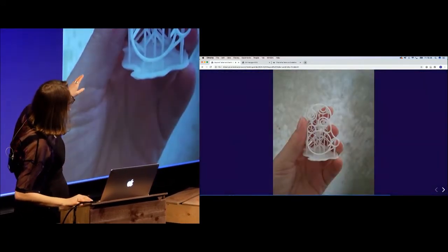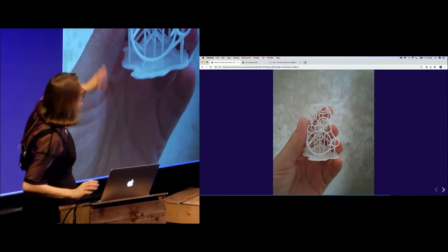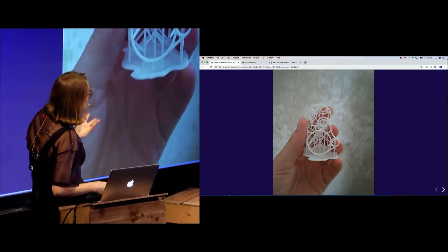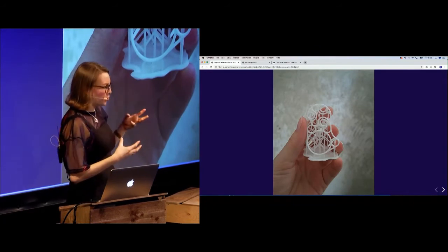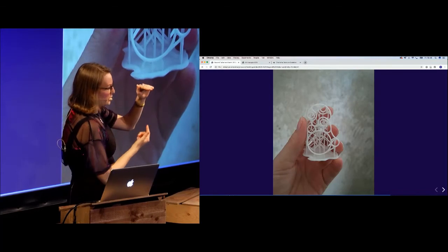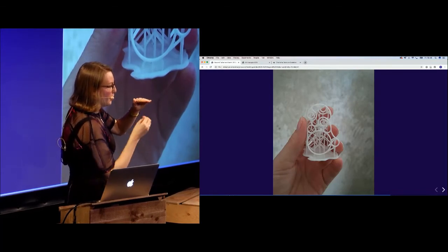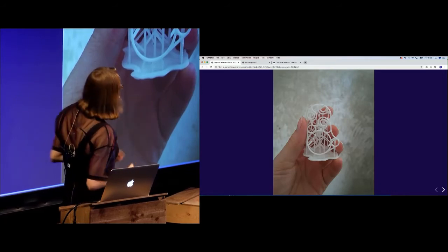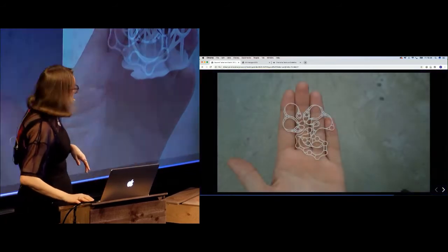So yeah, this was the first model, just in plastic, not in wax, that I made from a Formlabs printer. You can see the kind of structure behind that. Those will support things, because you can imagine this is being printed upside down, and you can't laser just in midair. So you have to build something for the bit that you want to attach to, but it's removable.